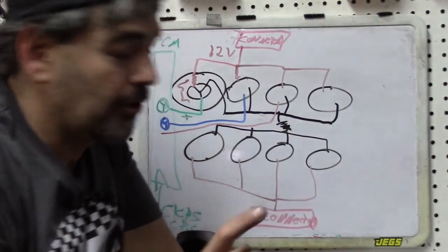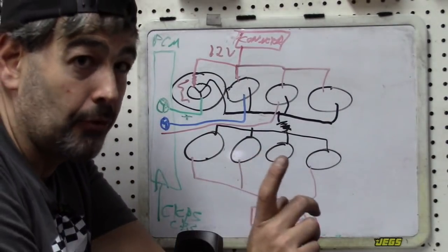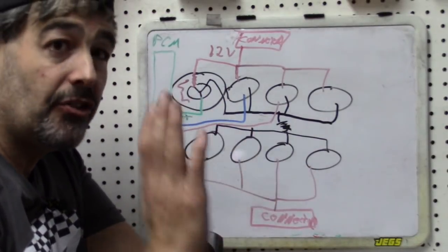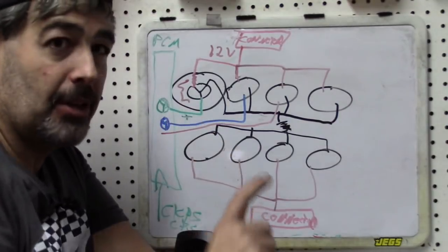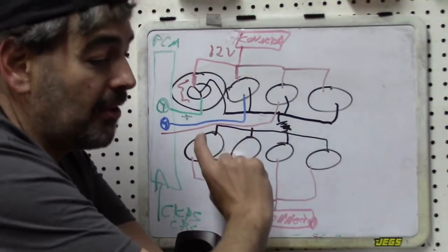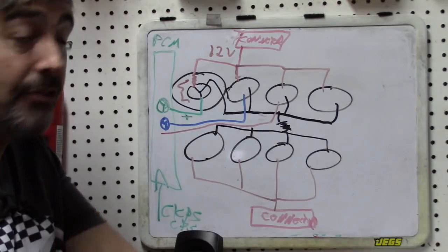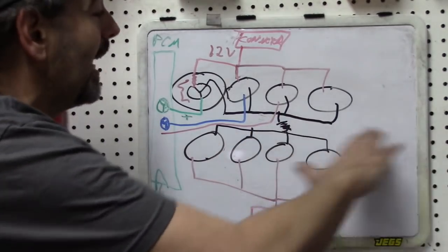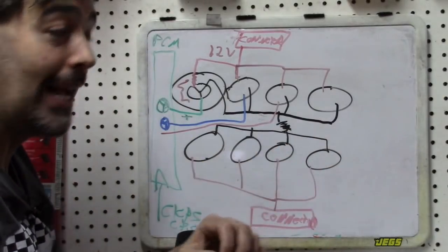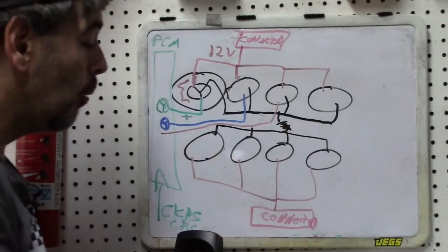That also, by the way, is going to create another complication on our scope waveforms if we try to look at that voltage spike when we stop our current flow. There will be a complication with that. We'll talk about that later. But basically, if you try to read that on this system, you're not going to see that voltage spike, and it'll all make sense to you in a little bit. It's because the switching is not occurring after where you're measuring that voltage spike. It's occurring before, because it's actually in that transistor. We'll get you there.